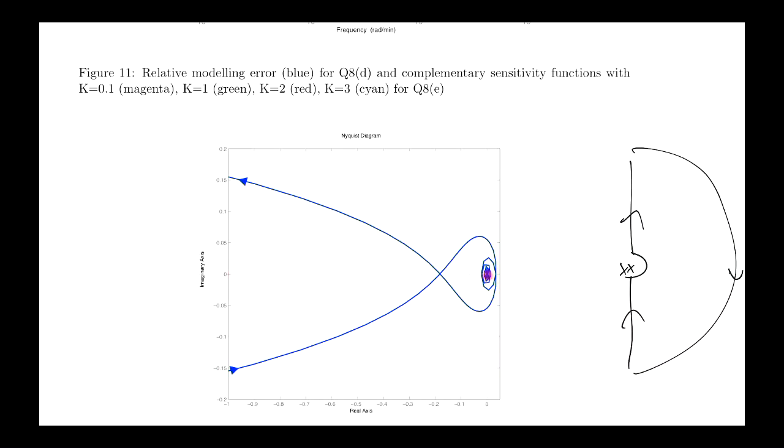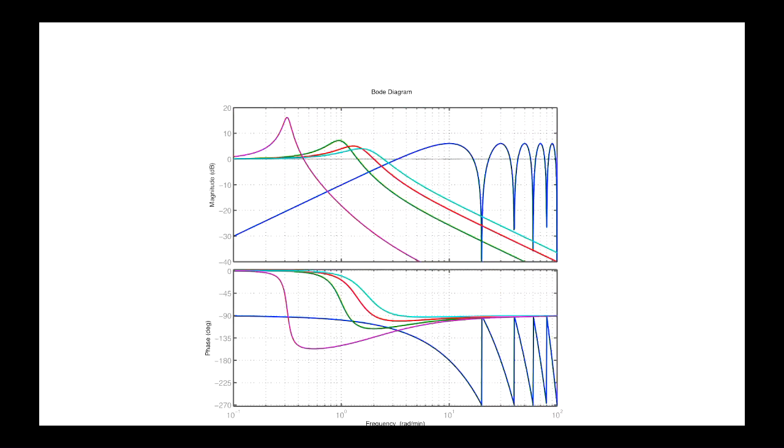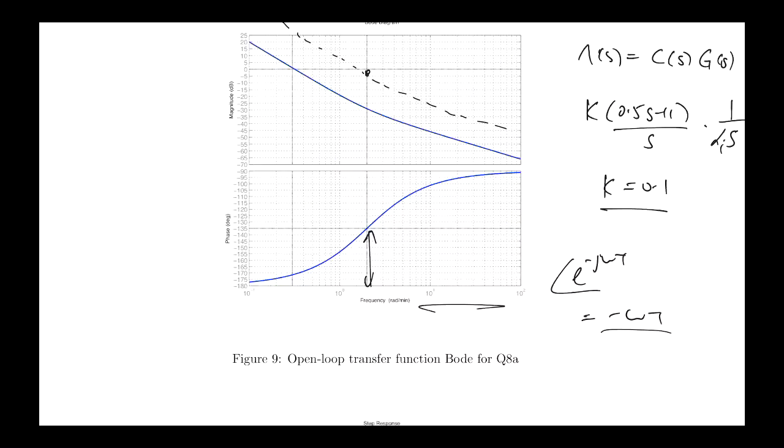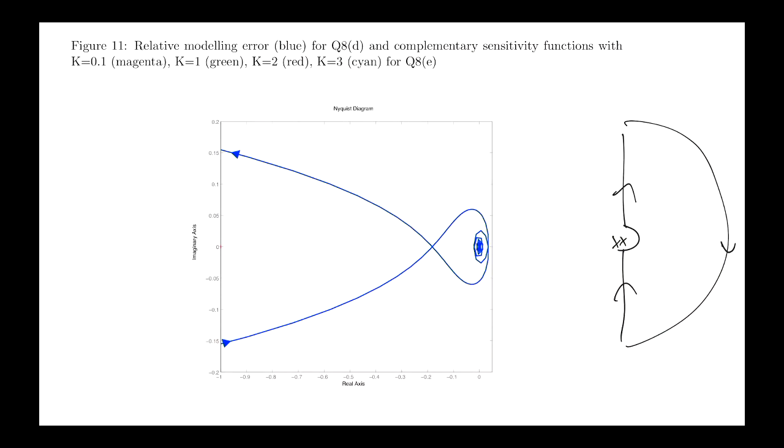In the complex plane, there's the origin. That's minus pi, minus 180. Minus 170 is not quite there. Minus 130 is somewhere around here. So this going down like this is consistent with the Bode plot moving up like this. So that's the direction we're moving in as we increase frequency, by moving up here on the Nyquist D contour.